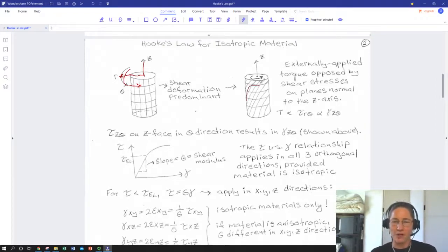And so we'll get some deformation that is not normal. So we're not shrinking it and making the radius smaller, making it a skinnier cylinder. We're not stretching it along its axis. We're not spreading out the angle theta, which is related to r. Actually, all we're doing is shifting this around. So it is important to realize when we're twisting and when we're stretching. So this is a pure twist. And in fact, a torsion test where you twist a cylindrical shaft or a ring is one of the easiest ways in material testing to make sure you're getting as pure a torsion, a pure twist, as possible without unintentionally inducing any normal stresses.